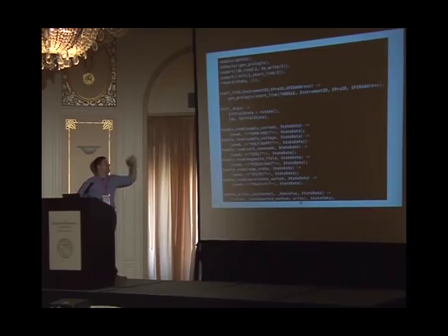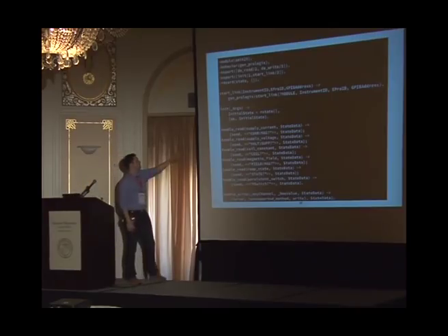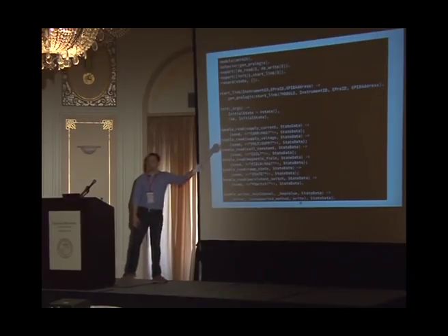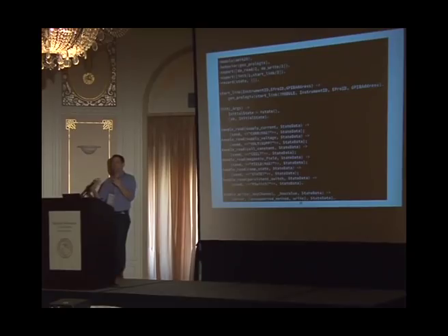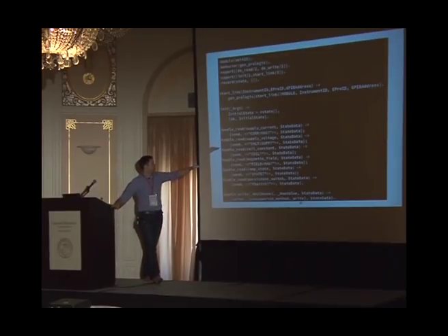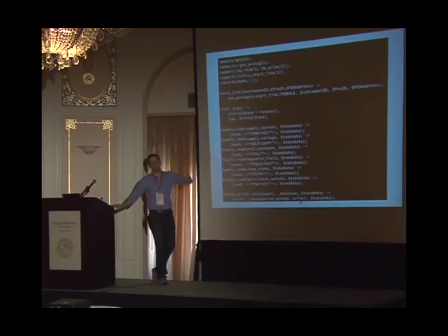So when you get a read, the handle_read function is called, of course, and it may be supply current or supply voltage or coil constant. So this is nice because these are very human readable, easy to understand names that actually wind up in your configuration database. So you'd say, I want this channel to be mapped to supply voltage on the AMI 420 instrument. And then when you interrogate that channel, you wind up in this function clause. And that function clause says, I want you to send to that instrument over whatever bus, in this case it's the gen_prologix bus, this string. And then of course the state data is returned.